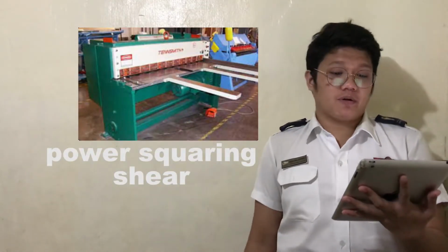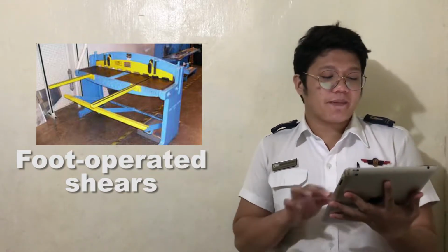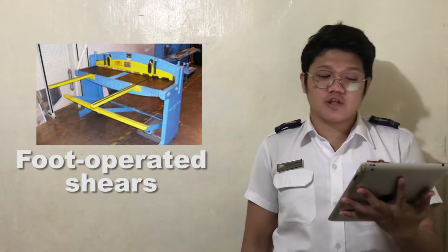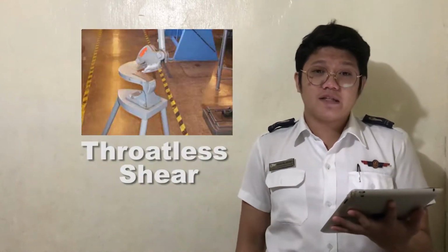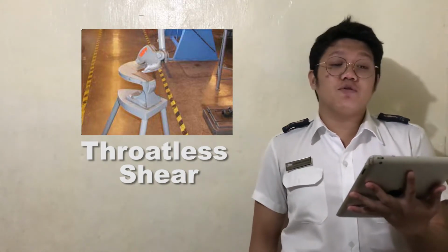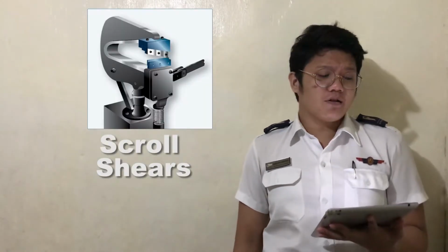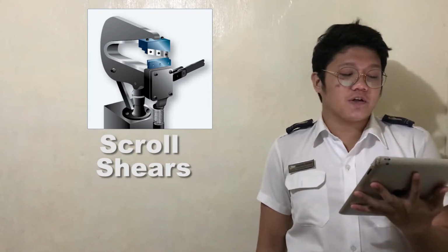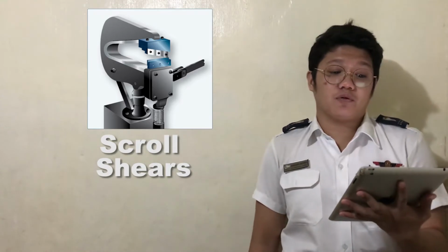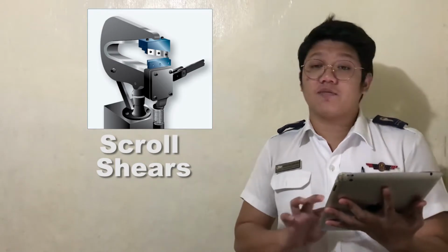This one is the power squaring shear. Foot-operated shears have a maximum metal cutting capacity of 0.063 inch of aluminum alloy. Use powered squaring shears for cutting thicker metals. Another shop tool is the throatless shear. Airframe technicians use the throatless shear to cut aluminum sheets up to 0.063 inches. The scroll shear: scroll shears are used for cutting irregular lines on the inside of a sheet without cutting through to the edge. A handle connected to the lower blade operates the machine.